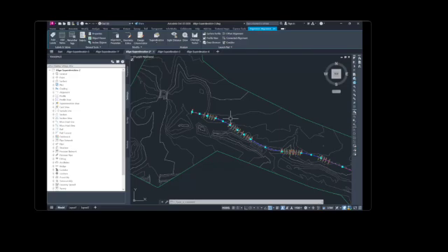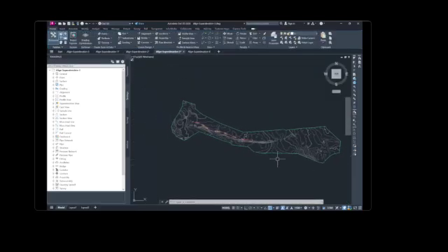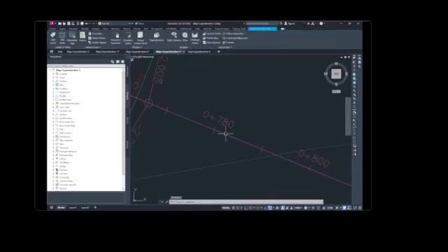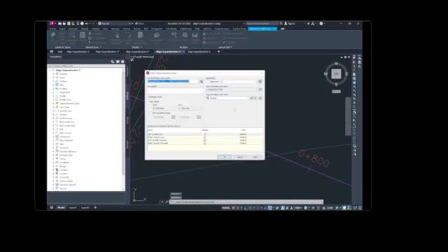to exercise 3, which is creating a superelevation view. So open the Align Superelevation 3 drawing. We're gonna select the alignment, Modify panel, Superelevation drop-down, Create Superelevation View. In the dialog box, the Superelevation View Style,